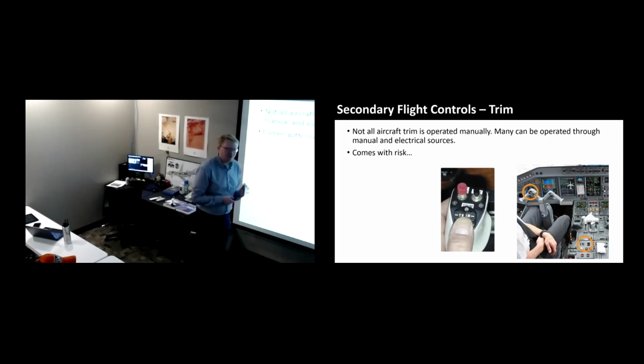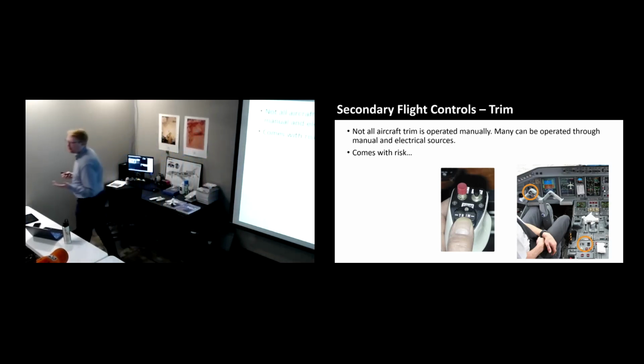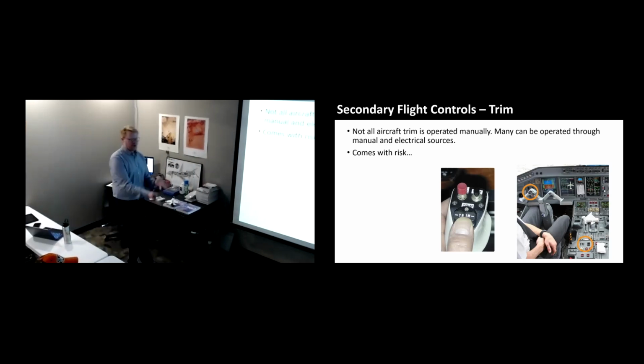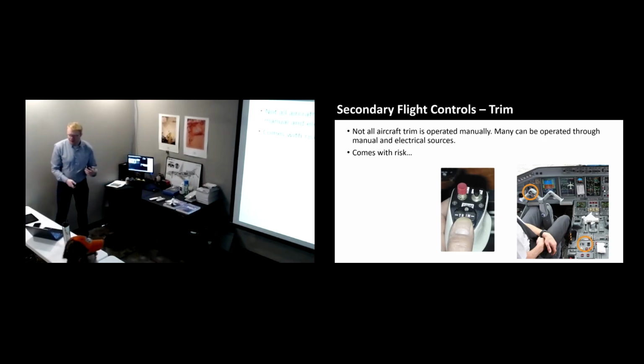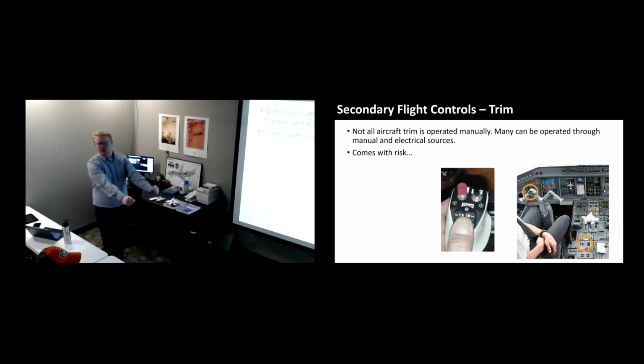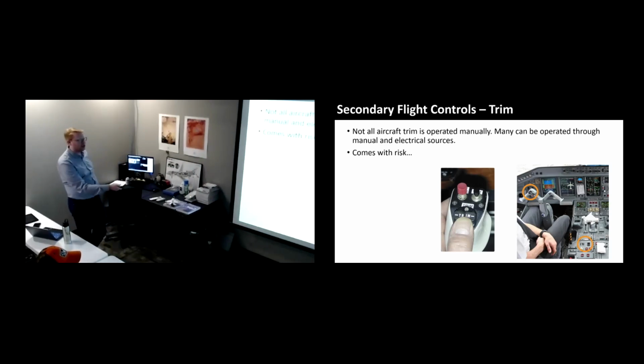These are little switches. If dust or dirt gets on the inside of them, the electrical contacts touch and they run. So if you're in flight and the trim contact gets connected and it starts running the trim, the airplane's nose will aggressively go up or go down. It's called a trim runaway. Pretty bad for airplanes because you pretty much lose the ability, like you'll be flying along in cruise flight, the nose will start going up, you push forward and it keeps going up because that trim is still running it up just due to a contact issue here.